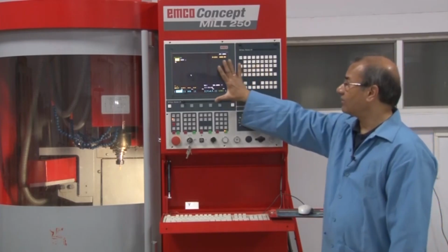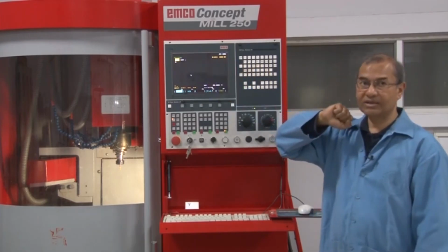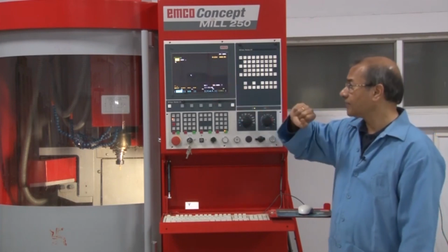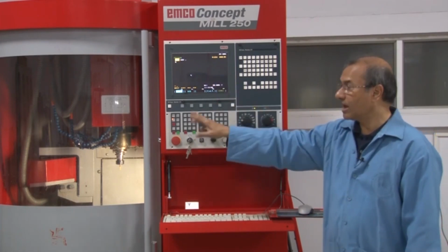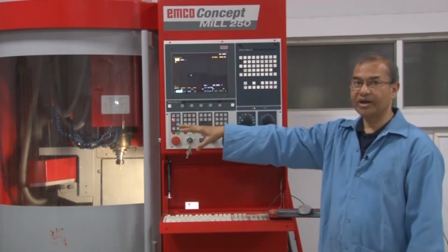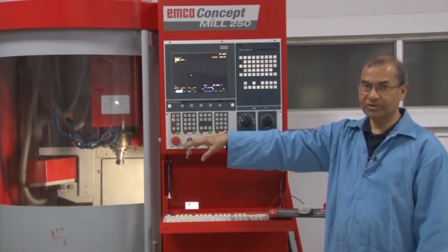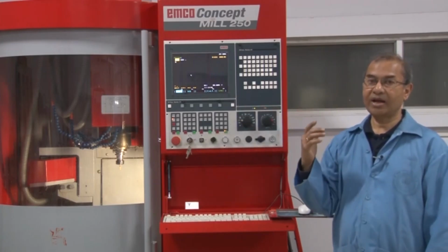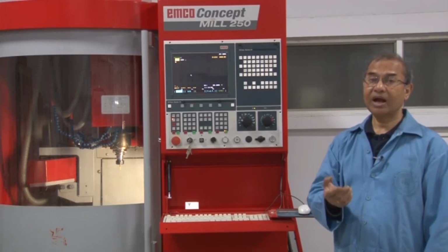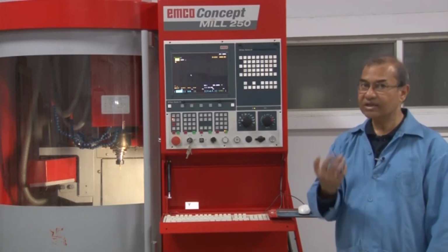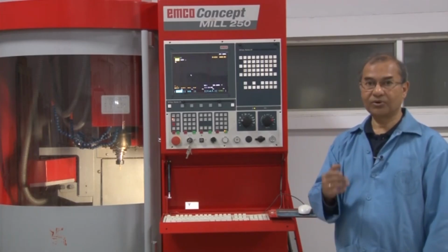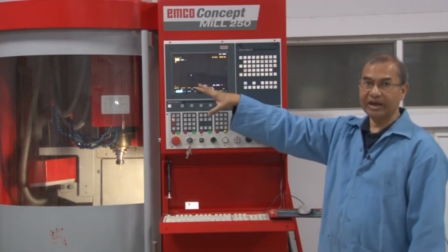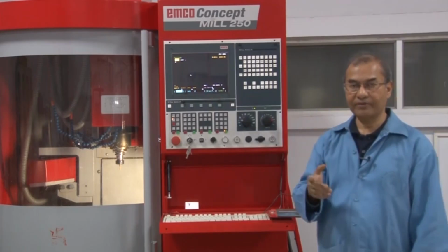Then when your program is made and input here, after that, when you switch on, according to the program, there will be relative movement between the tool and the workpiece. But before doing that, make sure that the program is right, run it in the simulator, and when the simulator shows no conflict in the program, only then bring that program, put it here and run it. So, that is only one part of it.